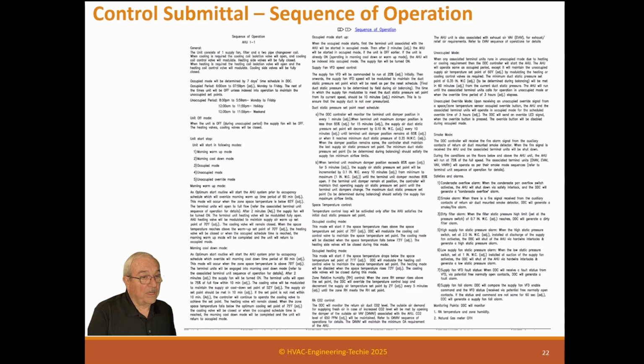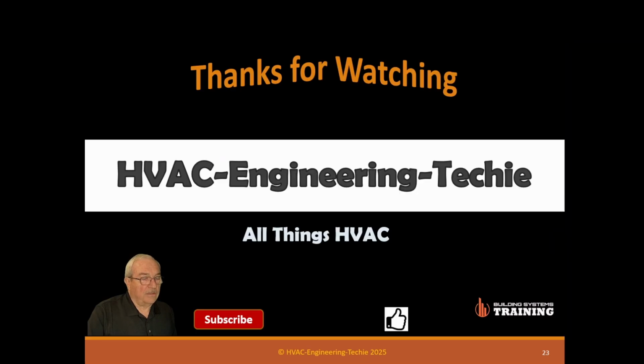So as a commissioner, when I get on a job and I see that, I start asking questions. And on a big job, with a lot of sequences or a complex sequence, I will ask for a sequence workshop. And we will sit down with the engineer, the programmer, the owner, and me, and we'll go through every sequence. And I'll have enough questions just to blow holes as big as trucks in that sequence, so that they have to come up with a sequence. And during that sequence workshop, we review all the issues and come up with a sequence. So this is the control that's in the submittal.